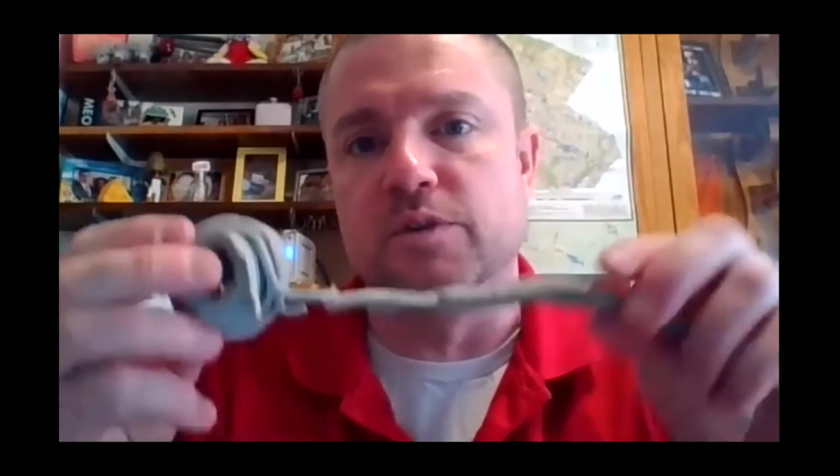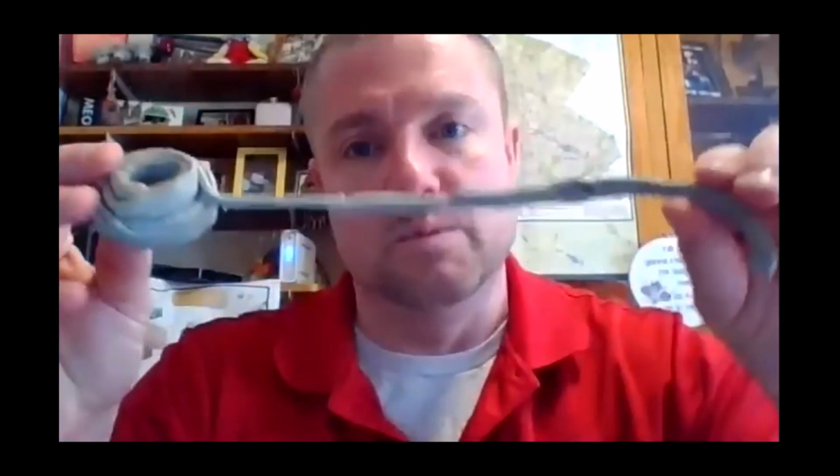Some other caulking products, I refer to them as peel and seal products. If you're a renter, these will not chip or peel paint. This is called rope caulk. Rope caulk is good, especially around a leaky window, and you're a renter worried about getting your security deposit back. Rope caulk can be a really handy tool, and I always see these in home improvement stores in the checkout aisle seasonally. They tend to pop up. A couple bucks, like $2, $3, you can get these. It's like silly putty, and it will not harm the paint.